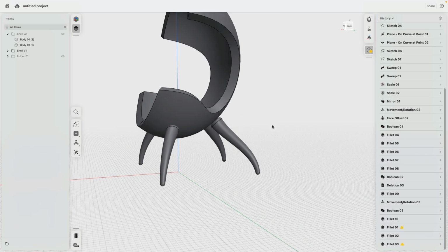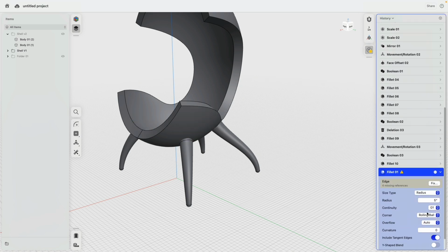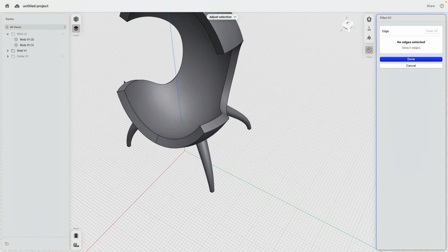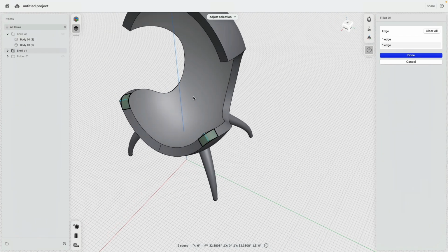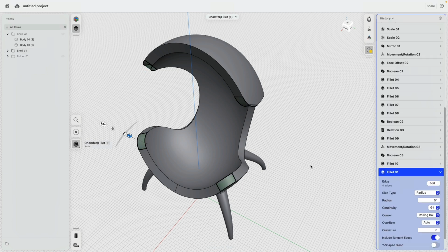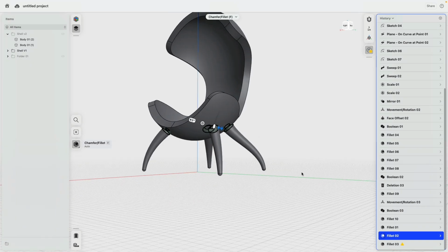Unsuppress. Oh, that's interesting. So that's that fillet that doesn't exist. So you are actually using the wrong edges. You should use these edges. I mean, it's good this mistake happened because I can show you how then actually we fix this stuff.